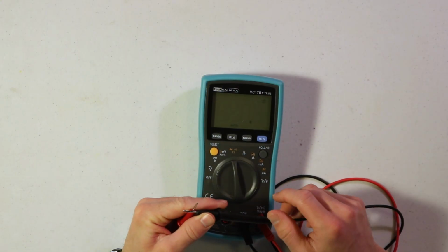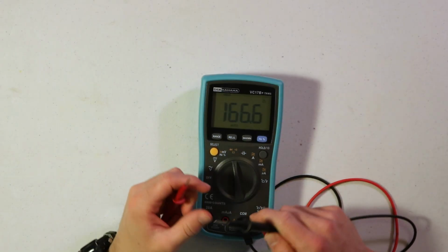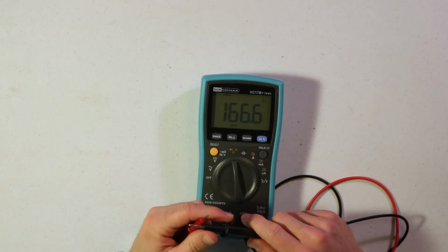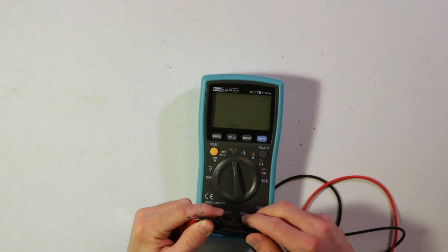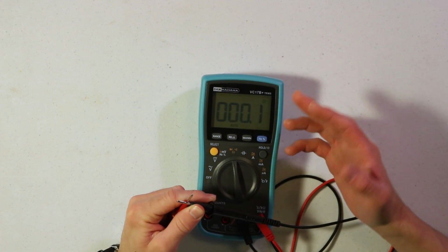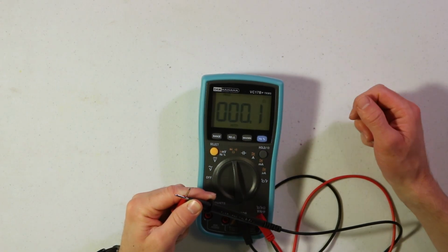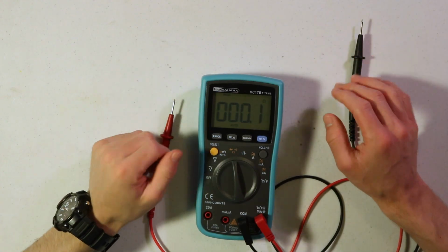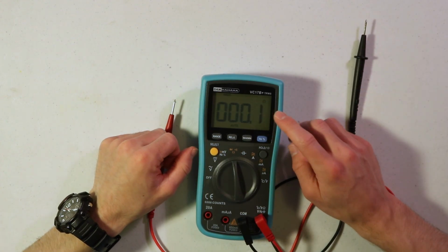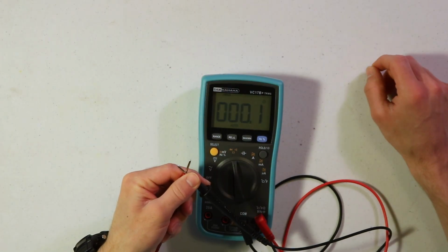But here again, if I touch this, press hold, it looks like I grabbed it while it was still ranging down, so that's not an accurate value. But I could hold this on here again, wait for it to reach 0, wait for it to equalize. If it was a different value, it wouldn't be reaching 0, but it reaches its final value, you press hold, then you can set the probes down, record your value, and you don't have to worry about holding your probes on the circuit and recording the value at the same time.